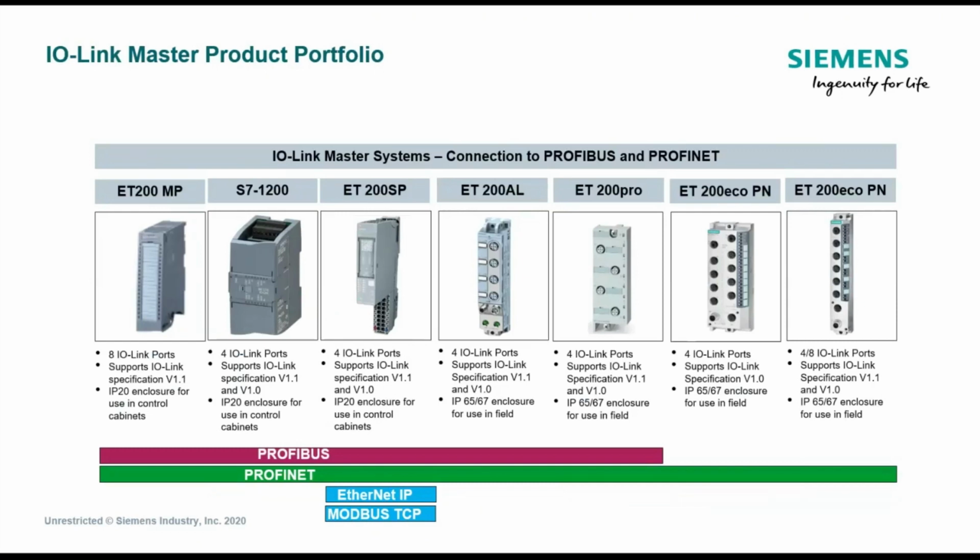Good question. Okay. One benefit I wanted to show with the S7-1200 I/O Link Master, from a replacement standpoint, is that if you lose a device, that's easy for the master to then download the parameters for the replacement. But what happens if the master fails? With the particular SP master, the configuration does not reside on the master itself.